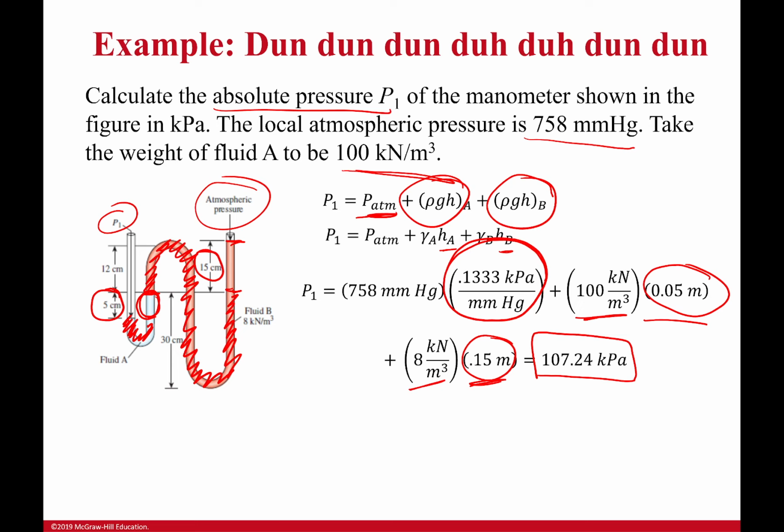And that's it. So just kind of recapping, when you have this kind of crazy U-shaped manometer, mark off all the sections that are matched, as in like it's a perfect U. So this section right here was a perfect U, this section right here was a perfect U, this section right here was a perfect U. Once you've done that, you know what you don't have to deal with. Those don't do anything because they're equal pressure on both sides, and so it's only the unmatched sections that do anything for your pressure, do anything for your problem, and it makes it a lot simpler to look at.